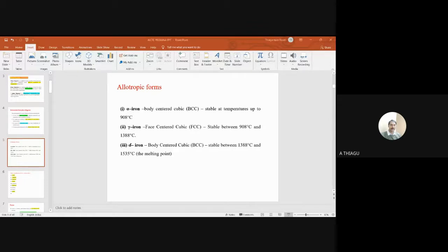So in all the cases, martensite attained the maximum hardness number. It is a very, very important microstructure. There may be some questions regarding the microstructures of iron carbon alloys. So my suggestion, please understand the different microstructures. 700 is the maximum Brinell hardness number for the martensite material. Maybe they'll ask one question regarding this particular area. Okay.